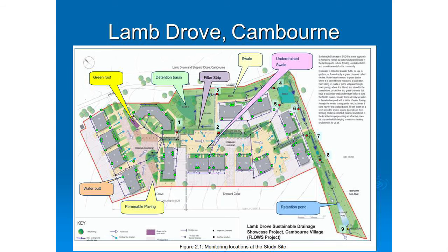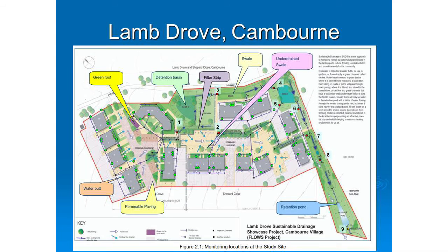At Landrove in Cambourne, which Fowler's been involved with, they've actually done some monitoring on a system. And this is a combination of engineered methods and green methods. So they've looked at the water quality and they've measured the water quality at various points within that system. So there's permeable pavements, there's filter drains, filter strips, detention basins, the whole thing. Some people just pick the SuDS manual up and throw it at it, don't you? But the important thing is this monitoring data that they've been collecting.